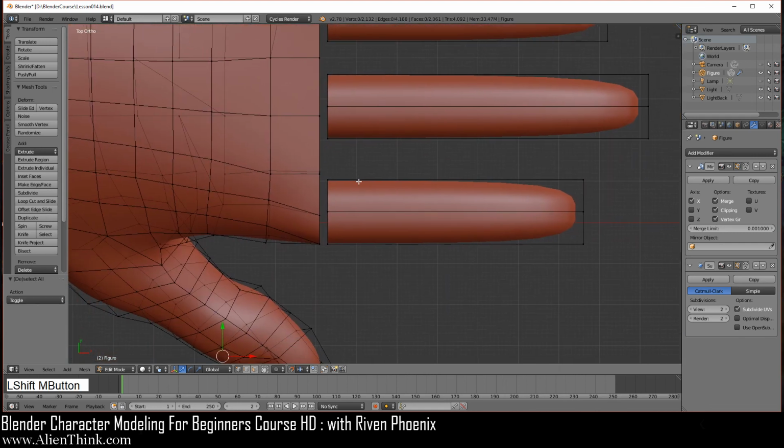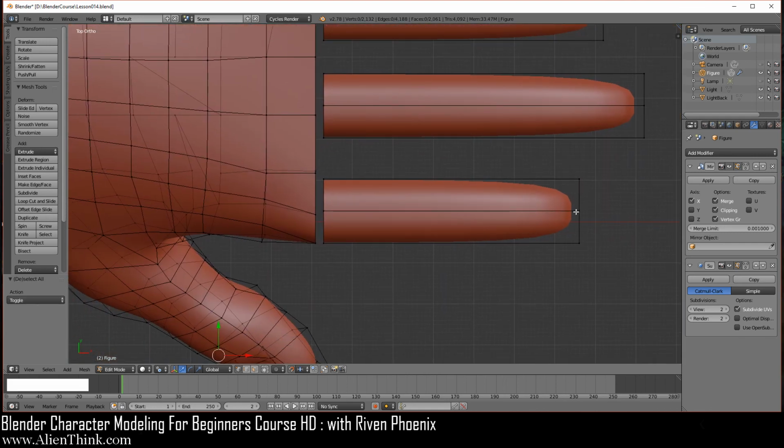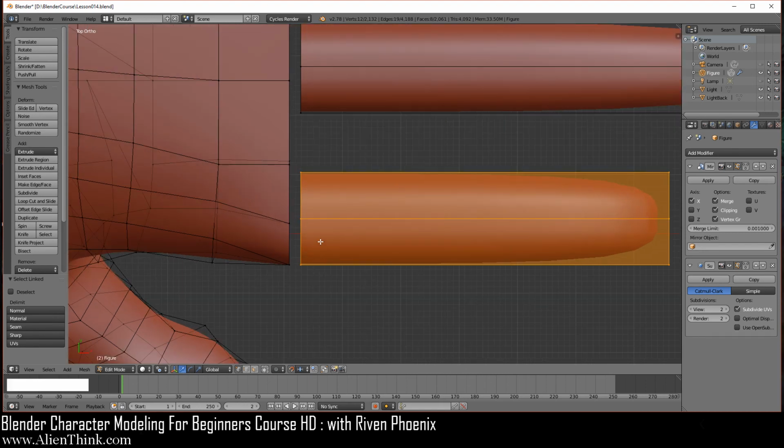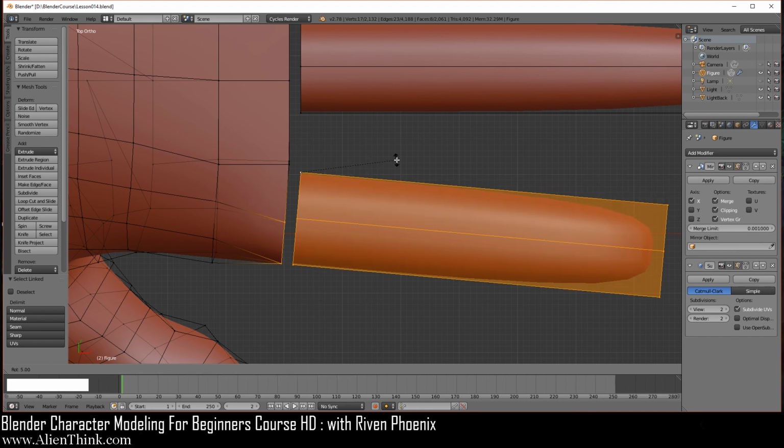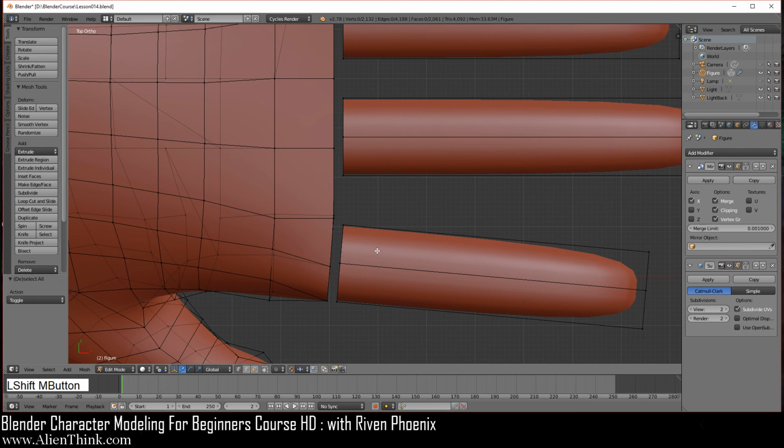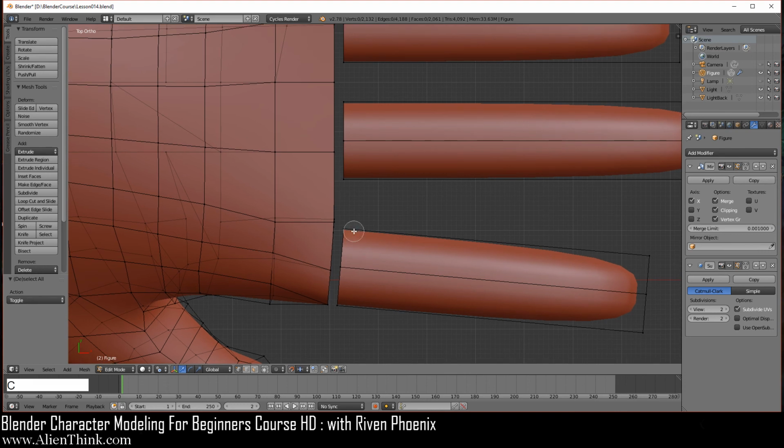I'm going to do the same thing over here. I'm going to do L to select this island, press the C key, select these 2. I'm going to shift, right click this one to deselect and reselect it back so I can visually see the 3D manipulator jumped over here. You're going to do R to rotate and then one time like this and then A to deselect. Okay, now we're going to press the C key again, click on this one, right click to get out of it. Now go ahead and switch this back to a median point.